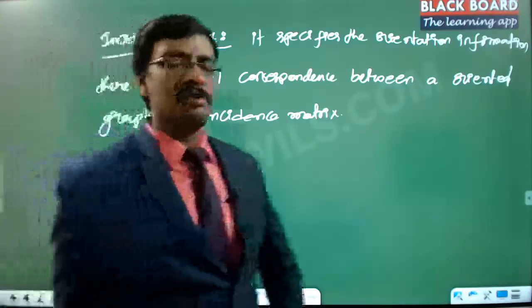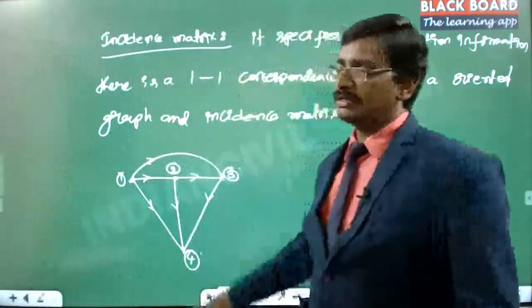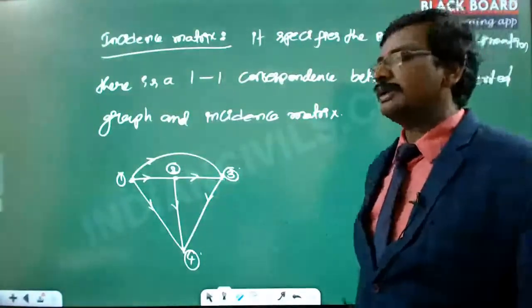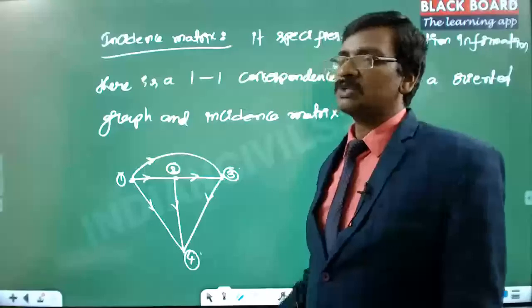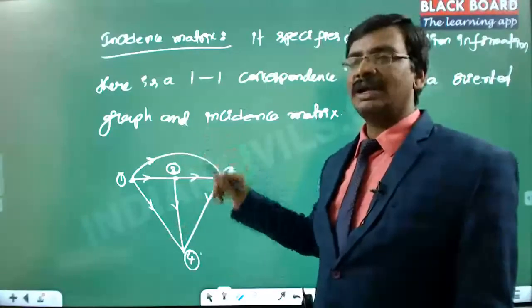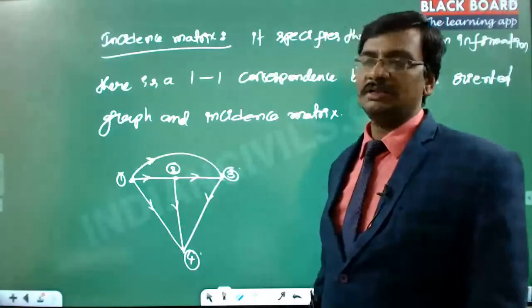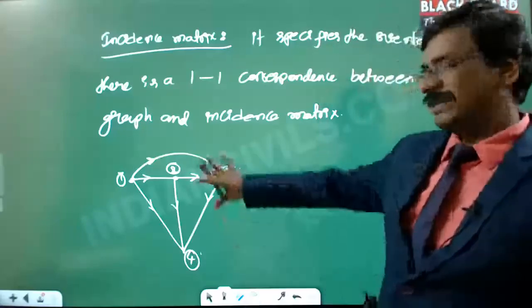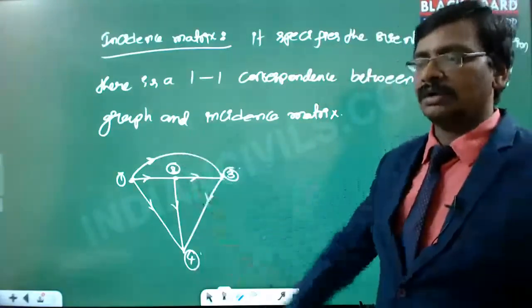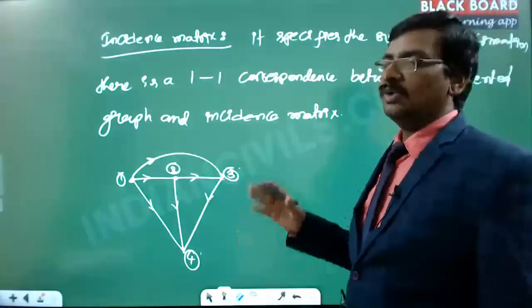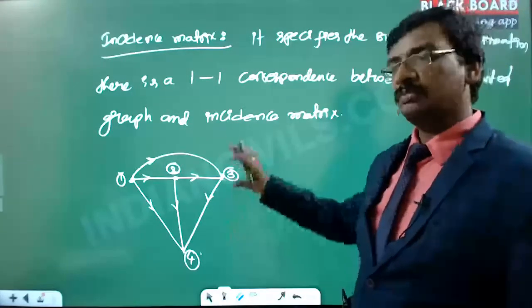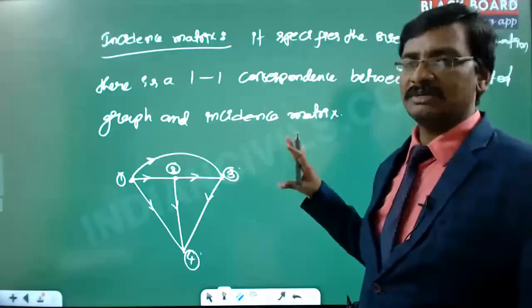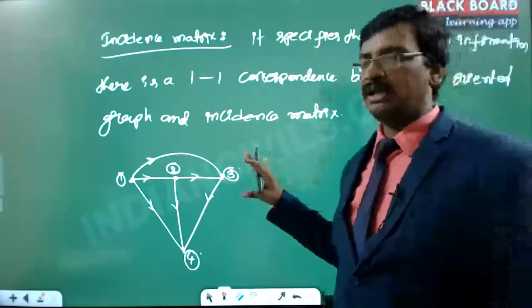These are any random directions that you can give, because based on this we will do the calculations. In reality, if the current given in a particular direction happens to be the opposite, then you will get the current value as a negative value. Other than that there is no difference. So you can give any random direction, and it is still an oriented graph. It may not be exactly that the voltage source is driving the current in this direction, but still the final result will come out accurately without any deviations.